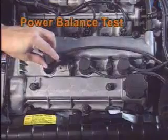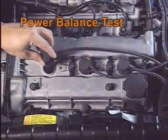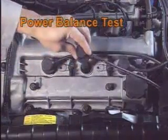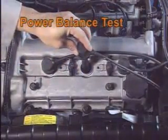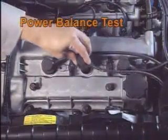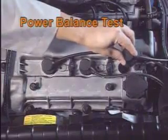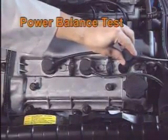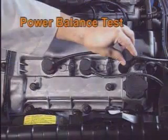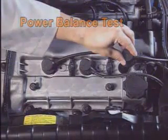For reference, when engine idle condition is not good, remove the high-tension cable from each cylinder one by one and perform power balance test, which compares the engine condition. Through this test, we can find the trouble cylinder, and we can solve the problem by inspecting the fuel system, ignition system, and combustion chamber pressure, which may influence the combustion in the corresponding cylinder.